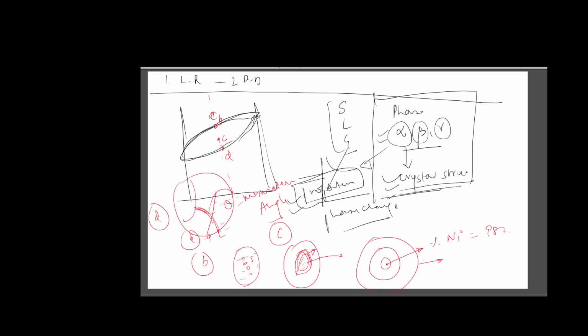Now, this was done by a researcher, and he found that if we cool from A to D, we can make some conclusions. If we decrease the temperature just by some units below the liquidus line to B, then solid starts nucleating in the microstructure at thousands of places.